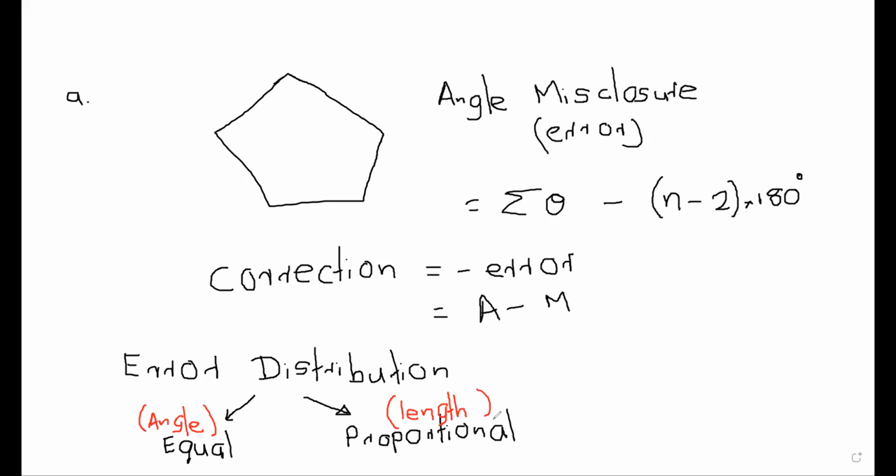So that is obvious. Let's say you have a tape, if you pull it a little bit higher than the standard tension, right? Let's say you have a 10-meter tape and you extend it up to 11. You take a large pull, then all your measurements would be multiplied by a factor 1.1 because you are extending 10 meter into 11.